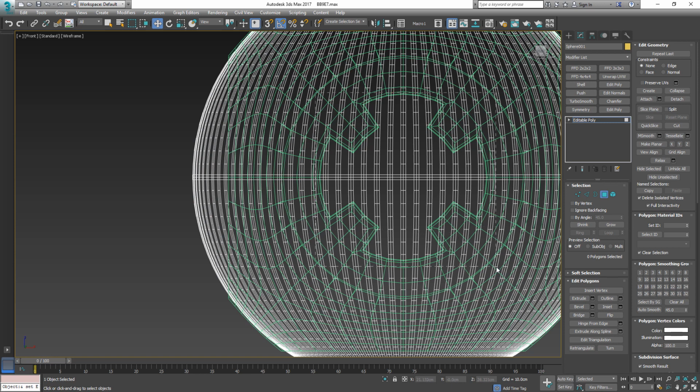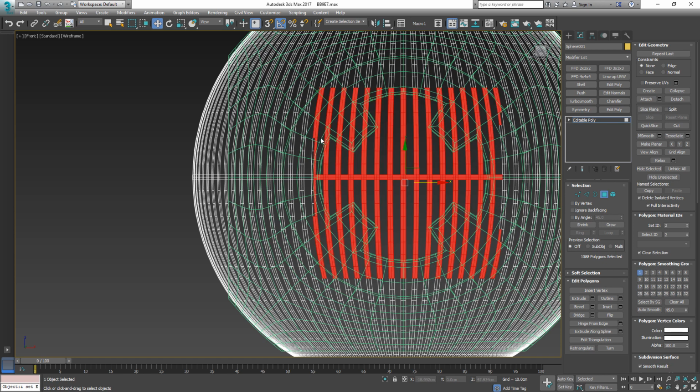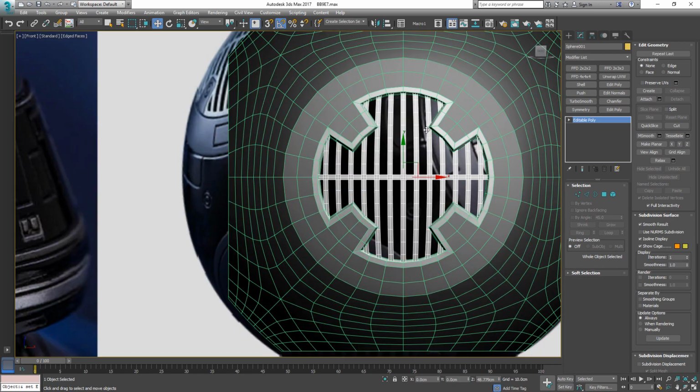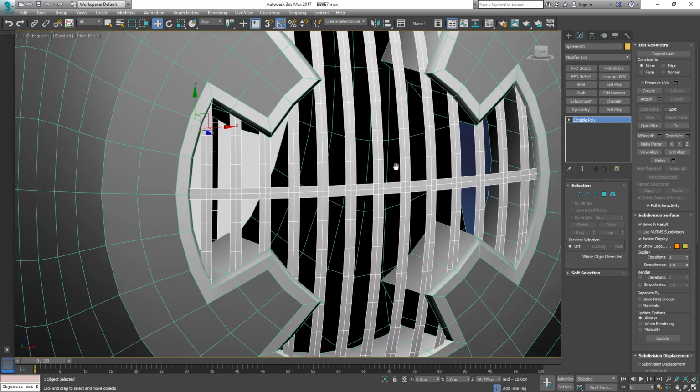And now I'm just going to draw a rectangular selection here, and some of the polygons we can add with Control if they didn't get selected. And this one here we don't actually need, so I'm going to press Alt, which does the opposite, then pressing Control gets rid of them. And now with that selection, we can press Control and I to make an inverse selection and hit delete, because that is really all that we need here, these polygons.